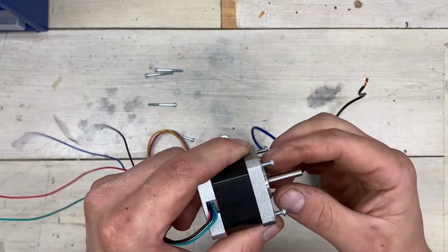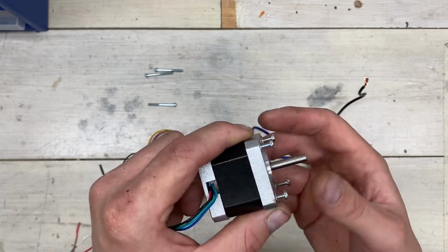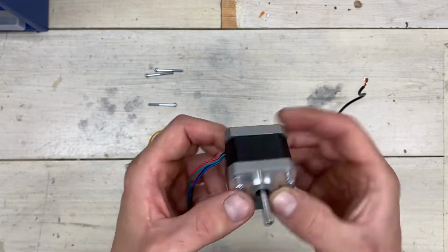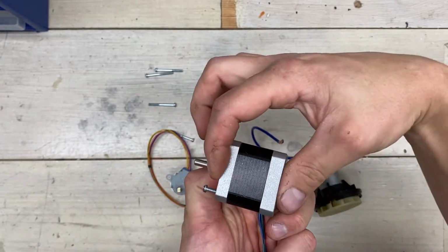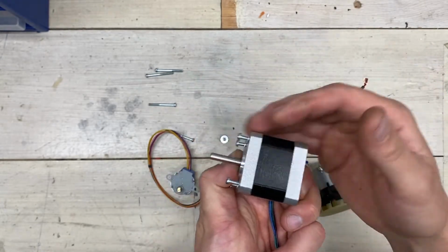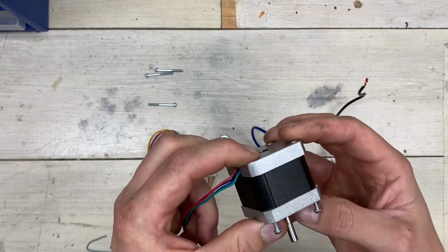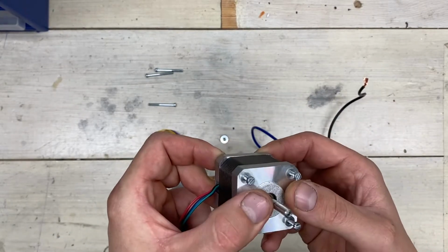However, there might still be different size shafts on motors in the same NEMA size. And also different power and torque ratings, usually depending on how long they are. So a thinner motor will have lower power and lower torque than a longer one, since there's less magnets inside. And let me open this up and show you what I talked about when there's a difference between these and BLDC motors.